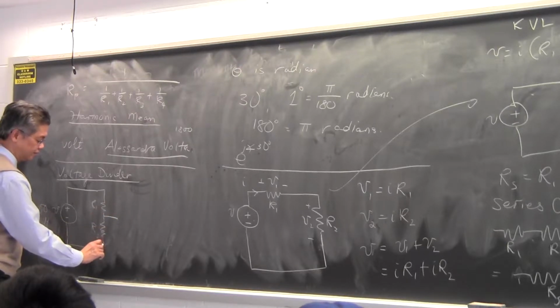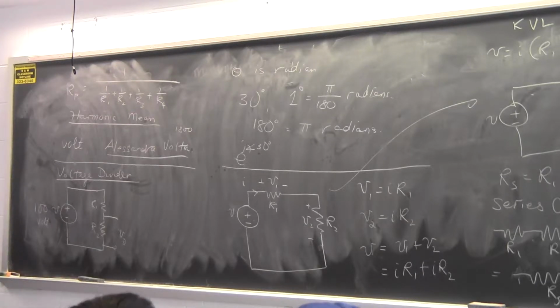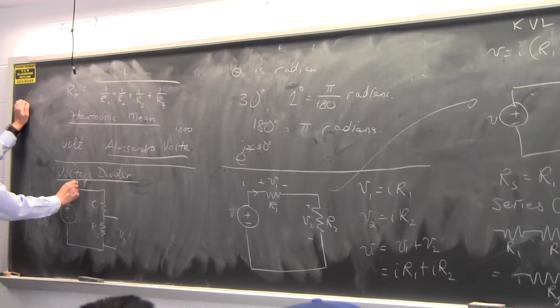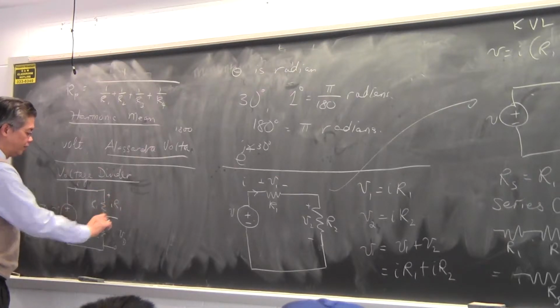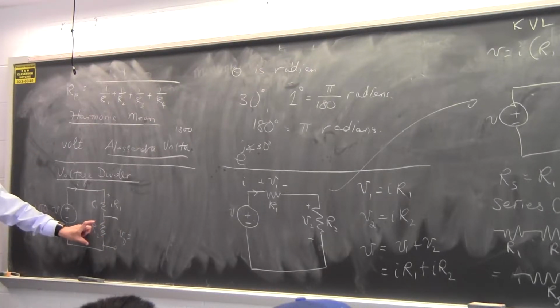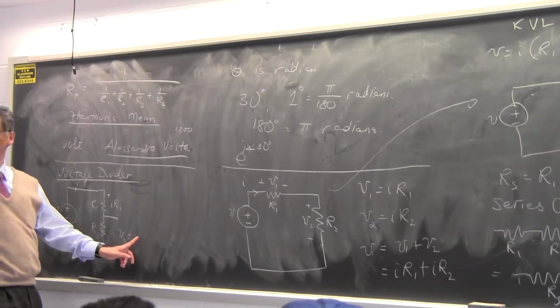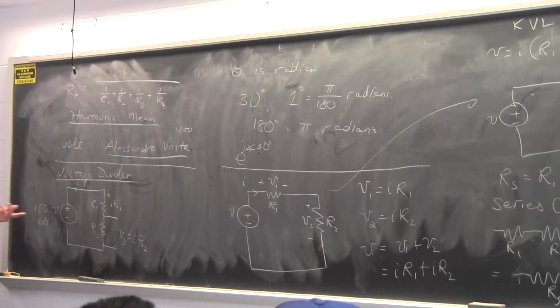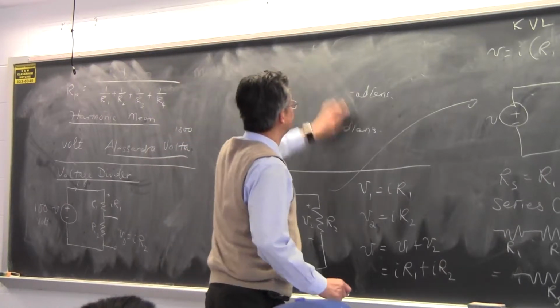You connect your device to this voltage instead of that voltage. And you can figure out what voltage across the device would be if you connect to it using this terminal, because there would be a current flowing through this thing. The first voltage drop is equal to IR1. What should be the second voltage drop across the second section? R2, very good. It should be IR2.